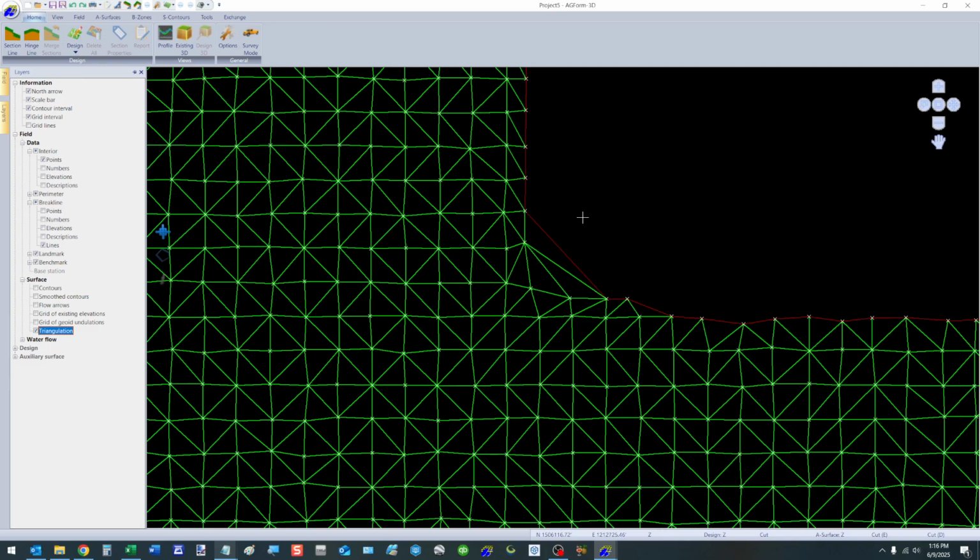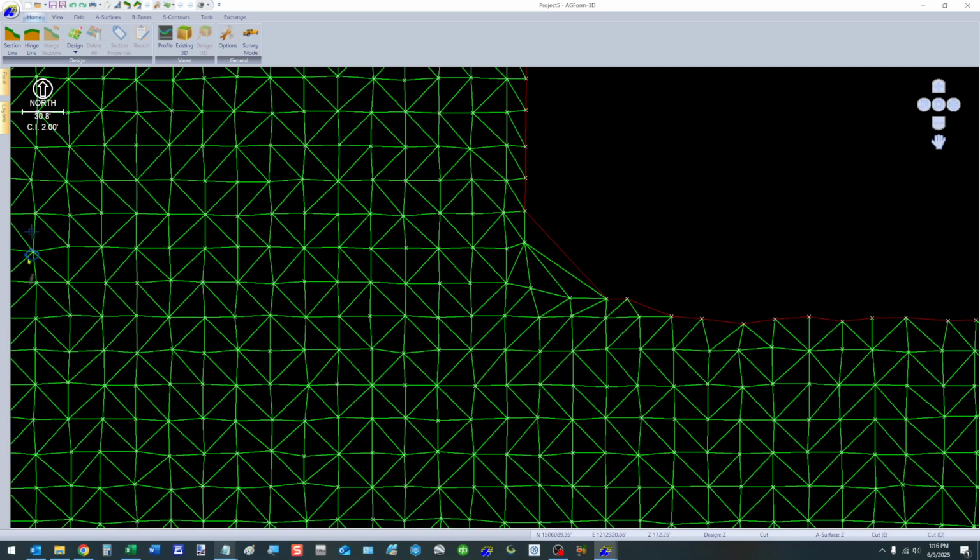So what you want to do, press the Control and Shift, and we're going to go over and choose this selection polygon, press Control, Shift, click once. Click, draw the line, come back out, connect it. Whenever it connects, connect it, then let go and press delete. And now we've fixed that corner.